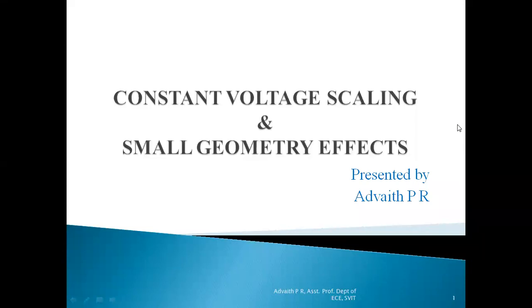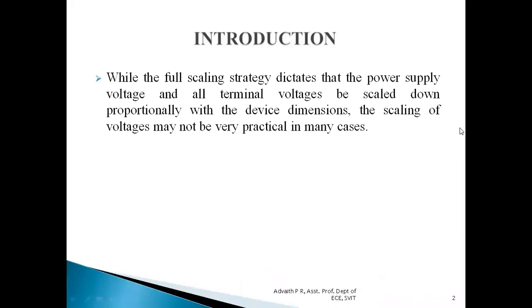In today's lecture video, I'll be discussing constant voltage scaling and small geometry effects. While the full scaling strategy, which was discussed in the previous lecture video, dictates that the power supply voltage and all the terminal voltages be scaled down proportionally with the device dimensions, the scaling of voltages may not be very practical in many cases. As we have discussed about full scaling in our previous video lectures, we have understood that all the parameters will be scaled down, including voltage. Scaling down of voltage may not be very practical in many applications.